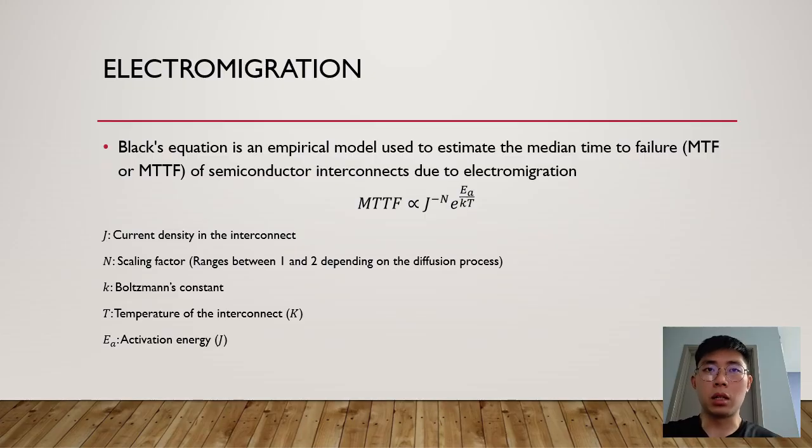Aluminum is alloyed with a tiny amount of heavier metal such as copper to increase the reliability. As a result, the sputter deposition method frequently employs a target made of an alloy like 95% aluminum, 4% copper, and 1% silicon. This offers electromigration resistance and stops aluminum from spiking. Other than that, the switch to pure copper for interconnects also improved the electromigration resistance.